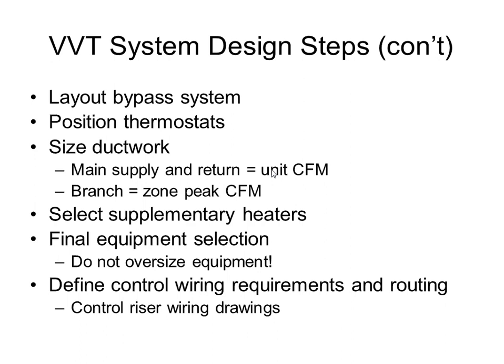Now that you have your bypass damper set up, you have your zone set up, you want to look at positioning the thermostats. Thermostat position is very important. You obviously don't want it exposed to any outer walls or any sunlight, anything that generates heat or cold, simply because that will throw off the reading in that zone, and that can throw off the whole system. If you have one zone that's reading super high or super low, that's going to affect the control of the rooftop unit, and because of that, you're not going to get proper control in the system.